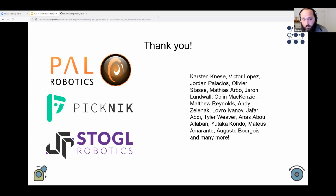We wanted to expand on that and allow the manufacturers to provide not only the URDF but also the hardware driver, so the robot hardware plugin, the system component that comes with their component, and its configuration. So you could have a Xacro file that only needs a little bit of tweaking from your side, but for the most part you just need to drop it in your URDF.